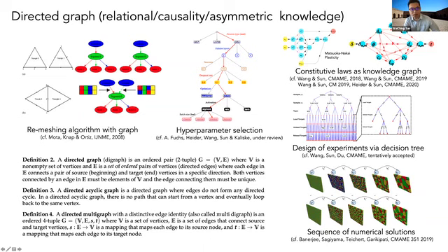So another type of directed graph that we have is a decision tree. Another application that I will talk about today is designing experiments. When we design experiments, we have a lot of different options to choose from. For example, in a triaxial test, we can control how much confining pressure we have, what the loading path is, should we do unloading, and if we do, what kind of combination do we want. If we consider all the possibilities together, it constitutes a decision tree. And each experiment is a walk in this tree.